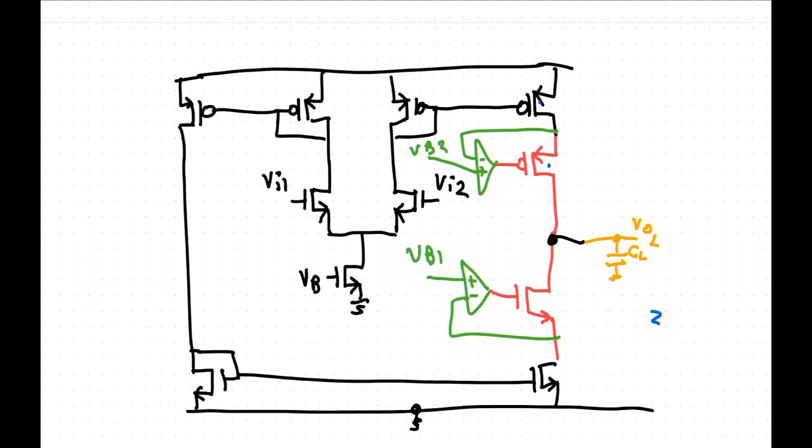Now when we do that, then we increase the output impedance by the gain of this amplifier. Well, that's what happened when we used that super cascode, whatever, last time. So that means that the output impedance has increased by that, which means that the gain has increased by that amount.